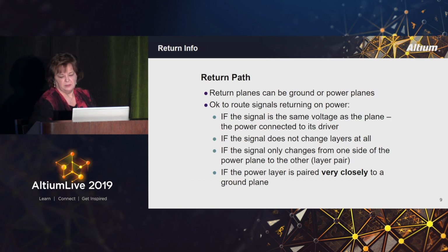The return path, the planes can be ground or power. We prefer them to be ground because that's the easiest, lowest impedance path to return. But I also need to admit that a power plane can be a return path as well, but there are caveats about that.